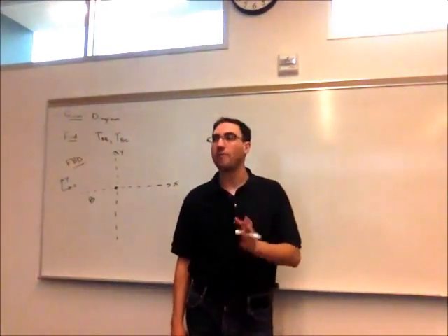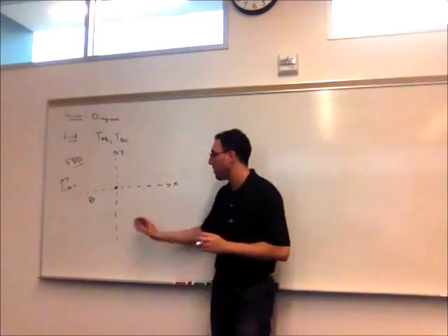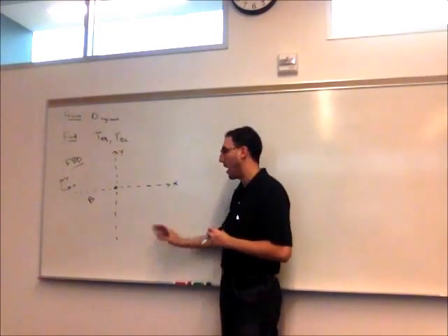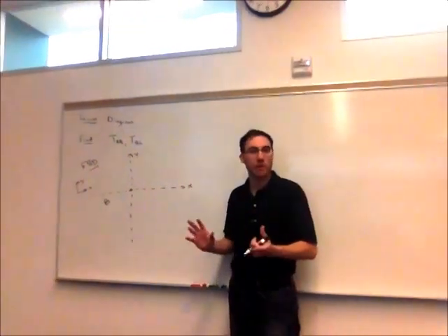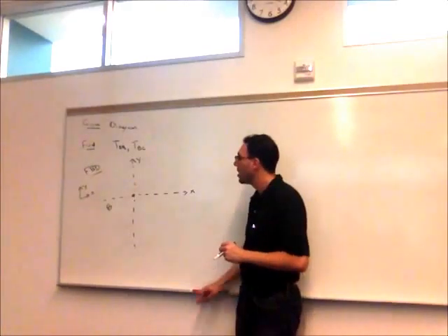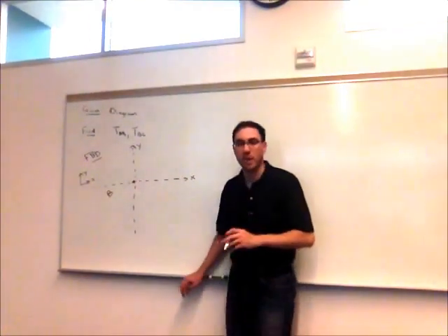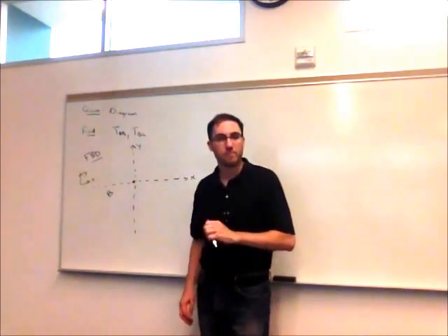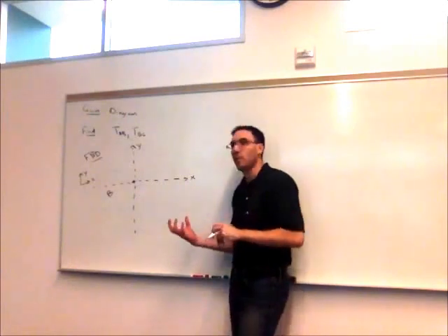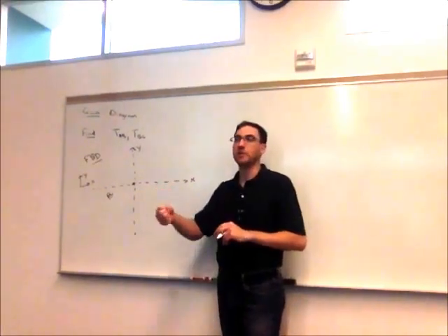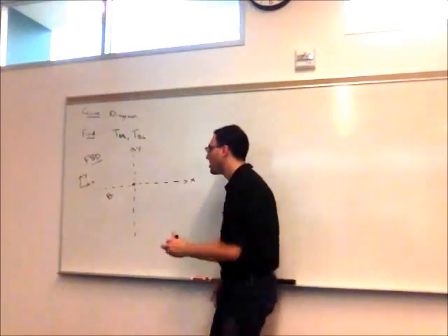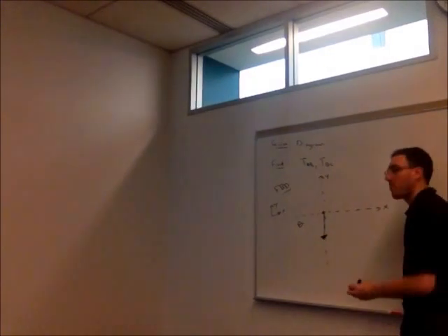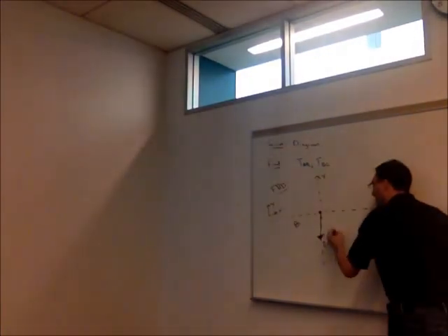Now we have to represent all of the forces that are acting on this particle. So again, we cut it away from the ropes, so we have to put in the forces in those ropes in this picture, and they're correct, well, if we know the correct direction. So what forces, and how do I draw them on this picture, act on point B? You have 200 pounds going straight down. Right, so that motor has a weight of 200 pounds. The rope it's attached to, therefore, has a tension of 200 pounds. So we can represent that, cutting away that rope, the force that rope exerts on particle B is 200 pounds straight down.